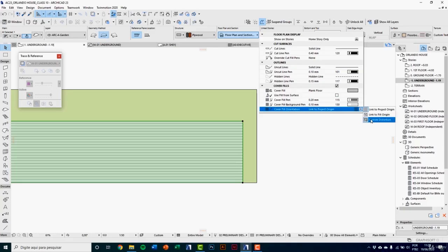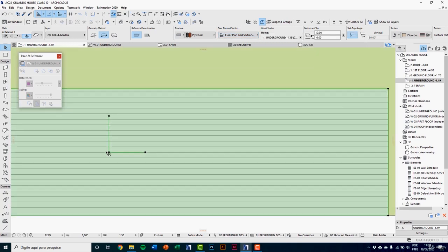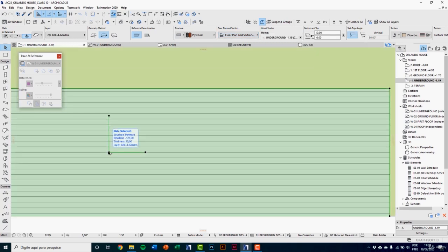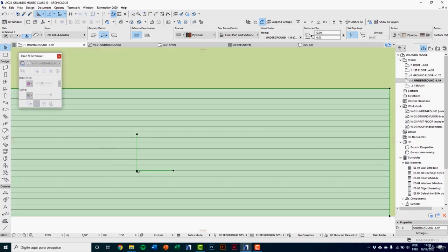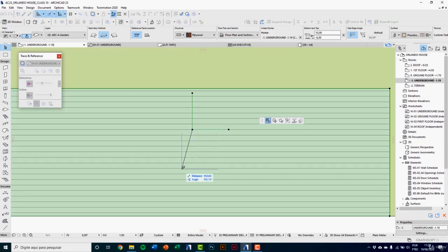We have the option Custom Distortion. An element indicating the origin point appears. Clicking on this point, with the option Move Fill Handle in my floating palette, I can move and set the origin point of the fill.